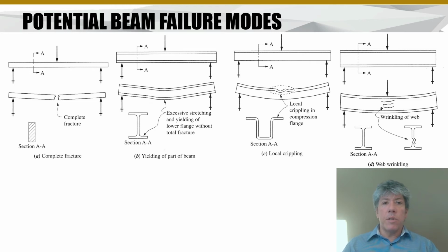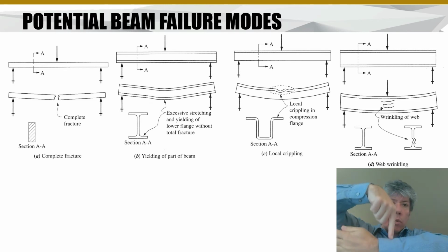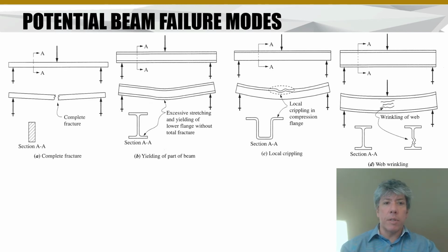So how is the stress itself distributed? Well, not surprisingly, as you move farther and farther from the neutral axis, where there is no stretching of the material, you find more and more stretching, so more compression at the top of the beam and more extension in the tensile lower section of the beam. And of course I'm thinking of a beam that's got a load acting down on it, typically from gravity or something. And so basically the stress is just distributed linearly from top to bottom.